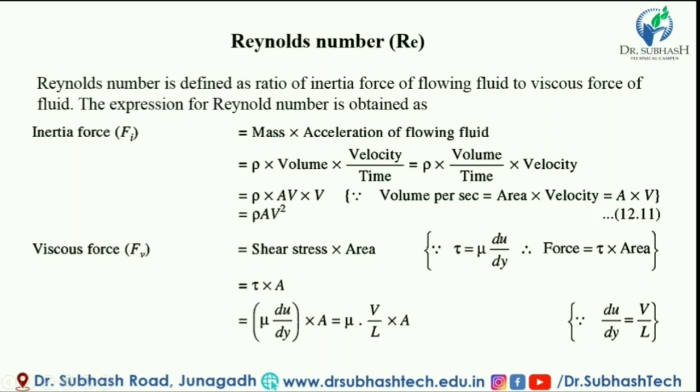Now the second one is the viscous force. We know how to get it: shear stress into area. Here the shear stress is developed due to the viscous force, and the shear stress equation for viscosity is mu du by dy. Here du is the velocity change and dy is the distance between the layers of fluid, the vertical distance.